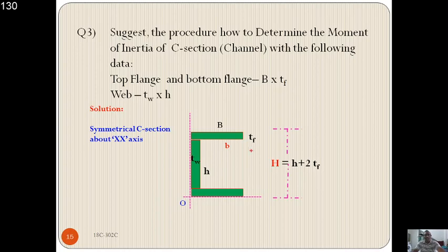Now inspect the centroidal axis. If you see that, this would be the centroidal axis. By observing, it is very distinct that both half portions are symmetric. Hence, y bar can be simply noted as capital H by 2. So due to symmetry, this would be the capital H by 2.